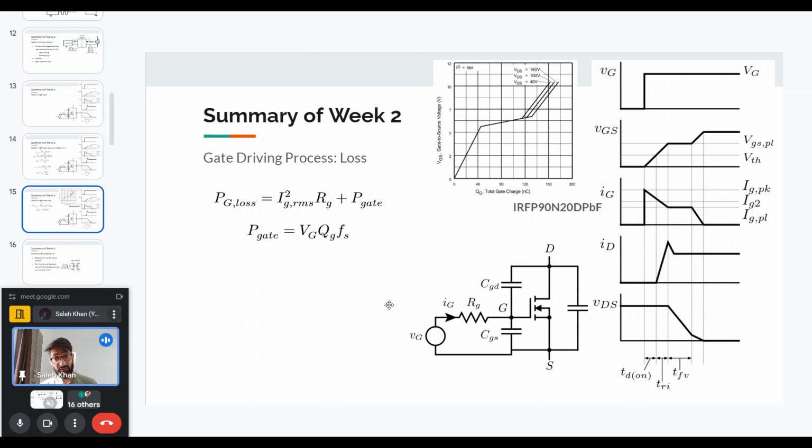If your switching frequency is high and you give a long dead time, then that will take away from your duty. So you take, let's say, the rise time and the delay time, and multiply by 1.5 times. That is a good starting point, and then you can see whether it affects the total on time of the switch.